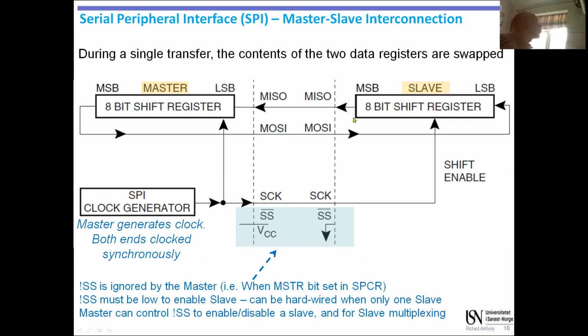Or if you're going to do it periodically, the slave just keeps reading the temperature value and puts it in here every time. And then the next time the master reads it, it will get the temperature value from the previous reading. So you could do this once a second or something like that. In your design, you do have to synchronize 2 different things going on here. One is that the slave device is creating a value of data, and the master is then clocking that data across. And the 2 actions may be independent, right?